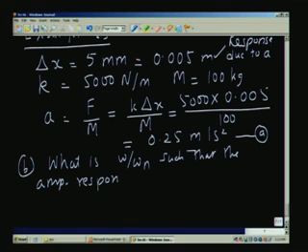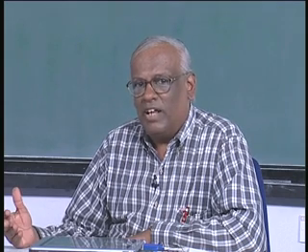The reason why I am working out this example is because it is going to tell us about the principles involved in acceleration measurement or in vibration measurement. So, amplitude response is 0.99, 99%. Of course, if the acceleration is linear, that means it is a constant value. Linear acceleration means the accelerometer is simply accelerated in a particular direction with a constant acceleration, that is, there is no periodicity, it is a constant value.